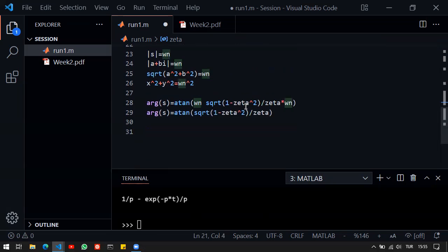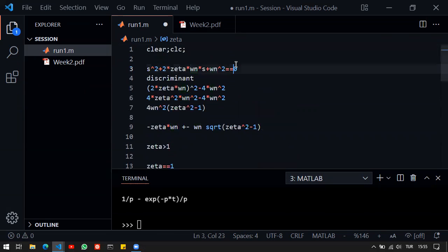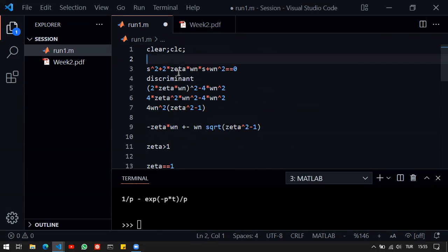Now, why is this all relevant? Because we know the settling time, overshoot, peak time, all the transients about this system. We know the second order all-pole transfer function so well that we will use it over and over again in order to design controllers. The second order transfer function is crucial to us.